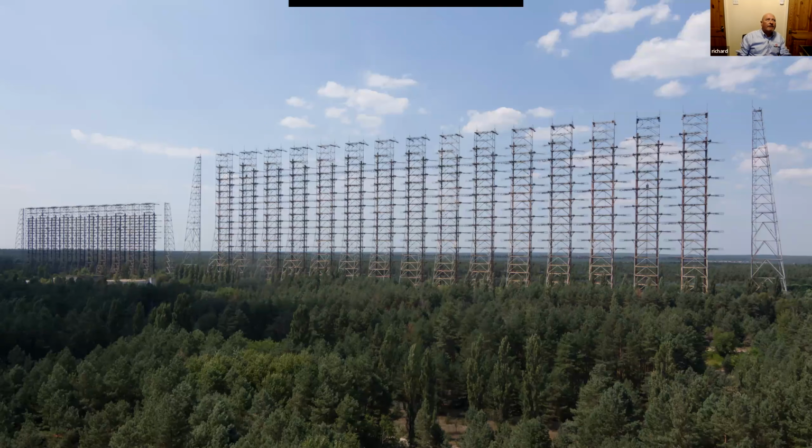I mean, the way that I tend to set my system up when I'm portable or going out is that I'll look for the beacon first. If I can see the beacon, then with the DX Patrol system, I know for a fact that it is locked on both transmit and receive. So if I can see something coming back, if I can see the beacon, I know I've got the dish aligned, and then if I QSY to part of the SSB section of the band, put a shout out, I should be able to see myself coming back on SDR Console. And if I can't, then I know I've got a problem.